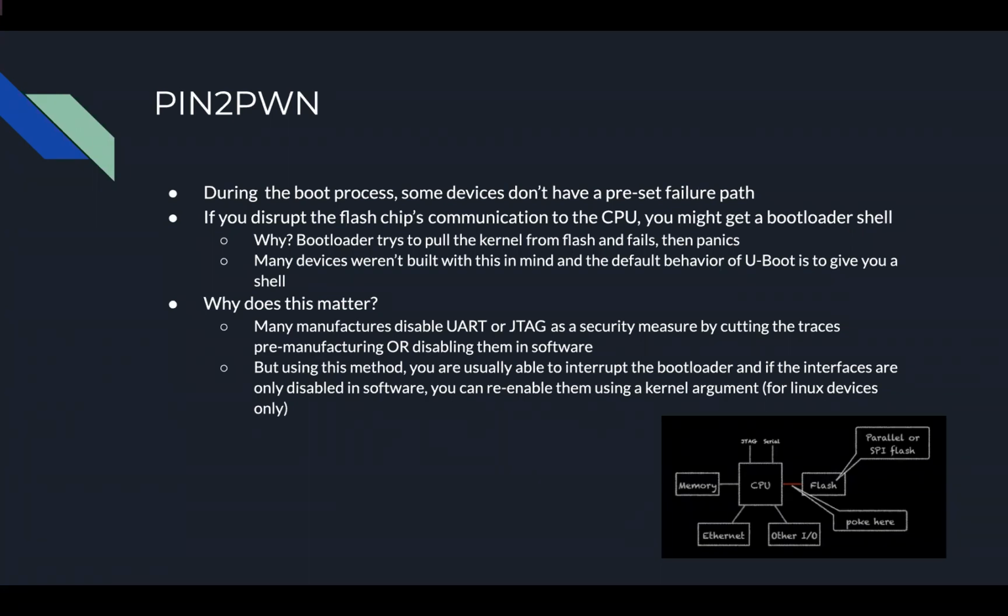And the way that you would deter this is to physically cut the traces in the PCB on UART or JTAG instead of just disabling it in software. But yeah, I've used this before. It actually works. It's really cool.